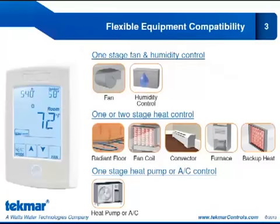The 553 can control up to 2 stages of heat, and those 2 stages of heat can have heat terminals of radiant floor, fan coil, convector, furnace, and backup heat. So unlike the 557 where your first stage of heat is limited to radiant flooring, on the 553 you can actually choose the heat terminals for each stage of heat if you're doing a 2-stage heat application. You also have the option to control a fan and a humidifier or dehumidifier. And we have the option to operate a 1-stage heat pump or air conditioner.